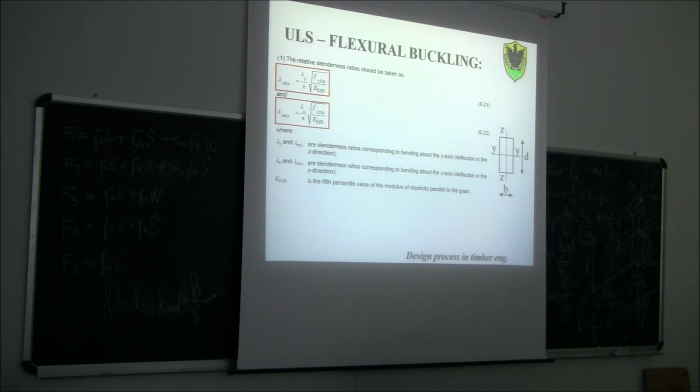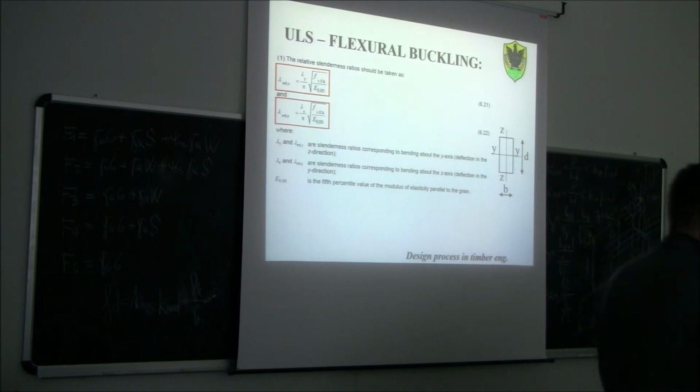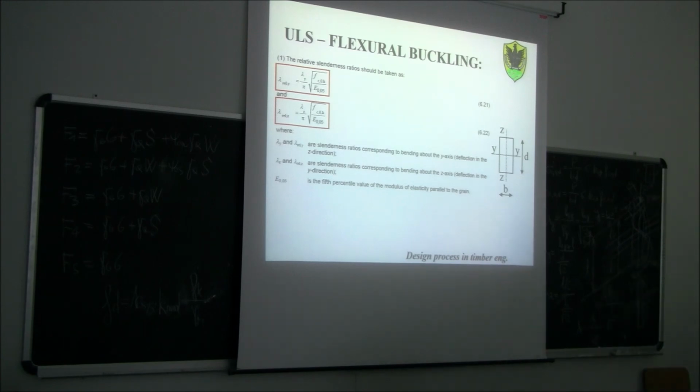I would like you to really understand this example very well, because in the course, very often you will have to make some choices in your design, some choices about the buckling length of your members. Because unlike reinforced concrete, in timber, almost always the design is governed by buckling or by serviceability limitation, not so much strength. So we need to be very sure about what you consider as a buckling length, axis of rotation, and so on. Are those two examples clear enough?